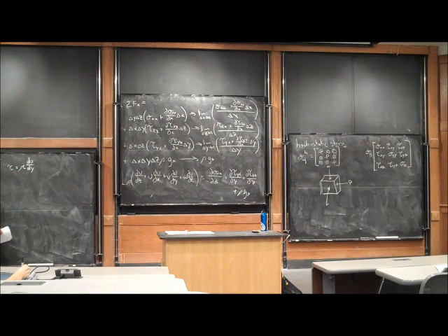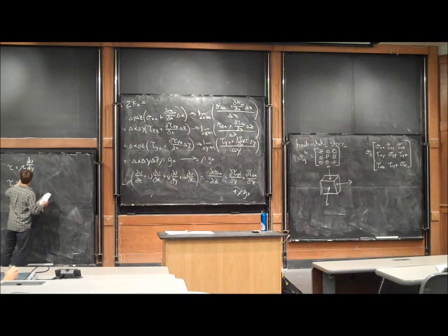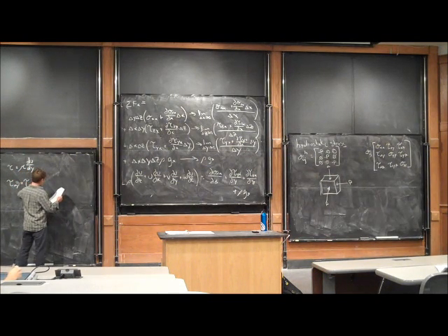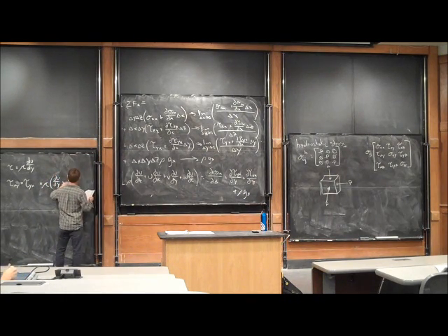We define viscosity for three dimensions based on multiple shearing, because we could also have shearing in this plane. This is a one-dimensional flow, so we only have one velocity gradient. So this was actually a simplification of tau xy, which is equal to tau yx, which is equal to mu times del u del y plus del v del x.